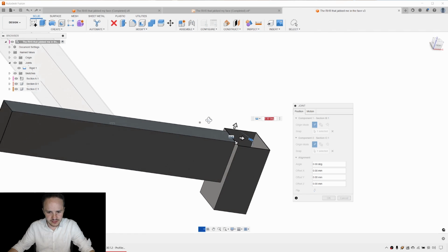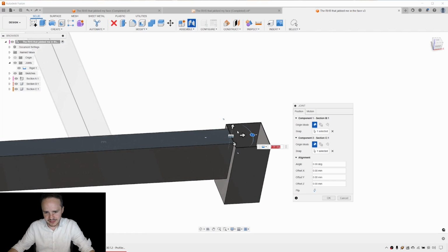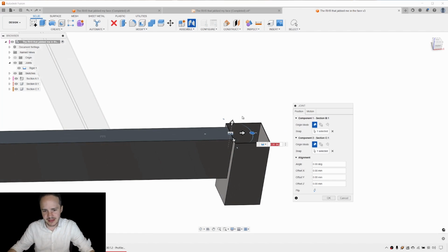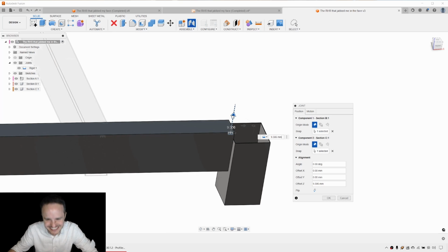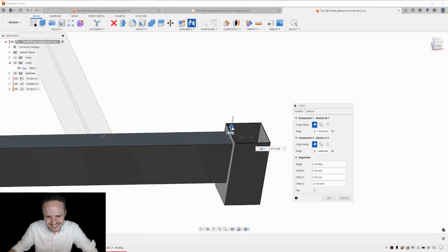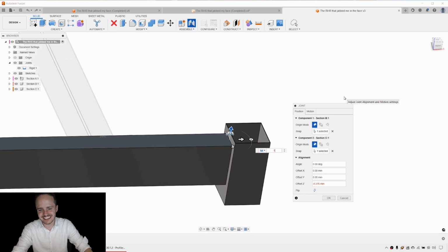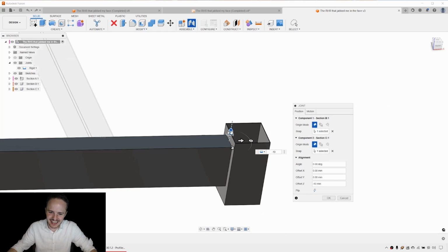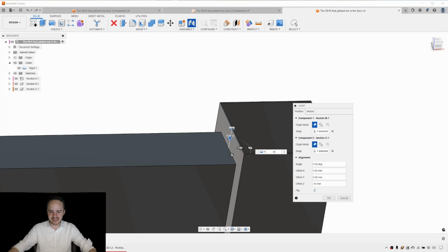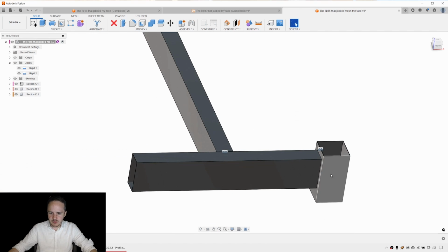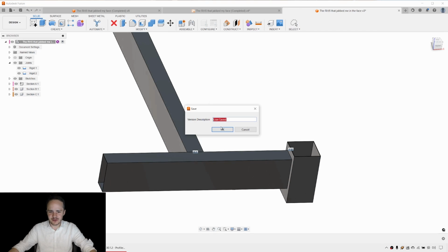There's one more thing that we need to change. We are going to have to displace this 10 millimeters upwards. So that's what we measured. To do that, all we need to do is click and drag this arrow here. Whoop! It went in the other direction. Click and drag this arrow down. And we'll say negative 10 millimeters is the displacement. That way we're creating a gap of 10 millimeters from the top surface here to the top surface there. Done. Go ahead and click OK. And now we've got a joint formally constrained. Wonderful. Save with a Control S.